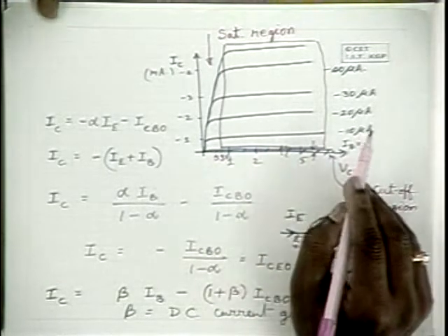By the side of this, we can also use a transistor for switching purposes. The transistor is either on, that means in the saturation region, or off, in the cutoff region. By operating the transistor in either the saturation region or the cutoff region, you can have binary level switching.